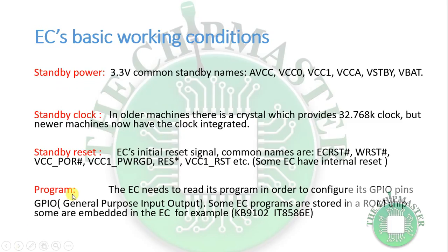Right, now we have the next one, which is standby reset. Yeah, the EC's initial reset signal. Right, common names are like ECRST, WRST, VCC-POR, VCC1 underscore power good, and RES, and VCC1 underscore RST, sorry. Right, some EC have an internal reset.